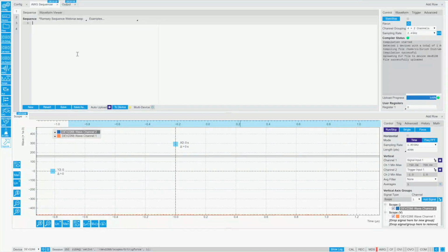Okay, so what you see here is our LabOne graphical user interface that can be used to control the instruments. Of course, everything which we do here can also be controlled by using our APIs through Python, LabVIEW, C, or .NET. What you see here on the left are the different functionalities. Currently, we are connected to the oscilloscope of the quantum analyzer. And you see here the different tabs, for example, the scope tab. If you click on these, then these open here and you see the additional functionality.